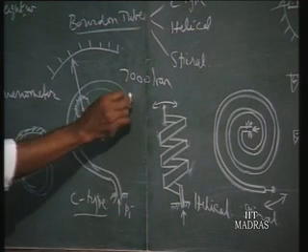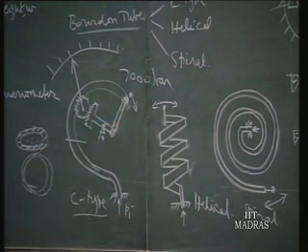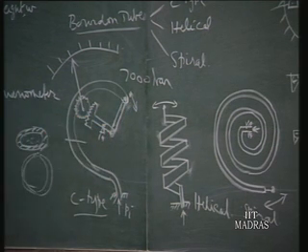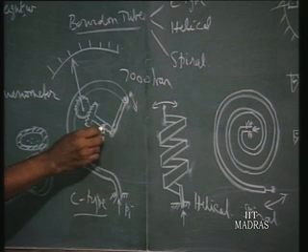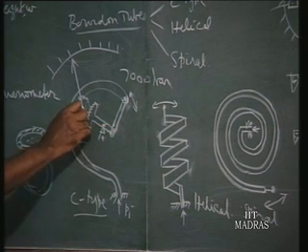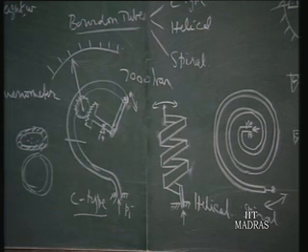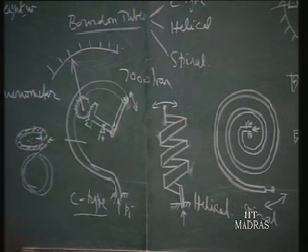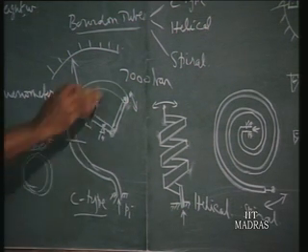In the process, this free end makes a motion. That free end motion is taken by linkages and given to a rack and pinion mechanism, with a lever mechanism pivoted here. The pinion axis is given to a pointer which moves over a calibrated scale. For higher pressures, the thickness is increased, and the cross section becomes nearly circular. For very high pressures the ovality is small, so when ovality is reduced, the amount of deflection is reduced.